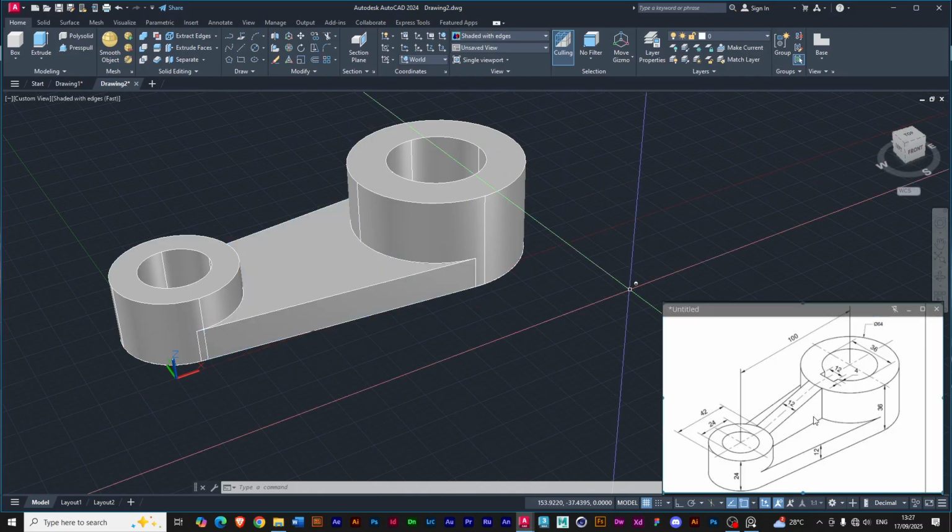Okay. Now to draw this one, it's not the wedge tool. We're going to have to draw a polyline, but facing front. We're going to change the UCS to face front so that we can draw this guy and extrude it. Is that a wedge? Yeah, this wedge. We're going to have to draw the wedge because we can't use a 3D wedge to get it.